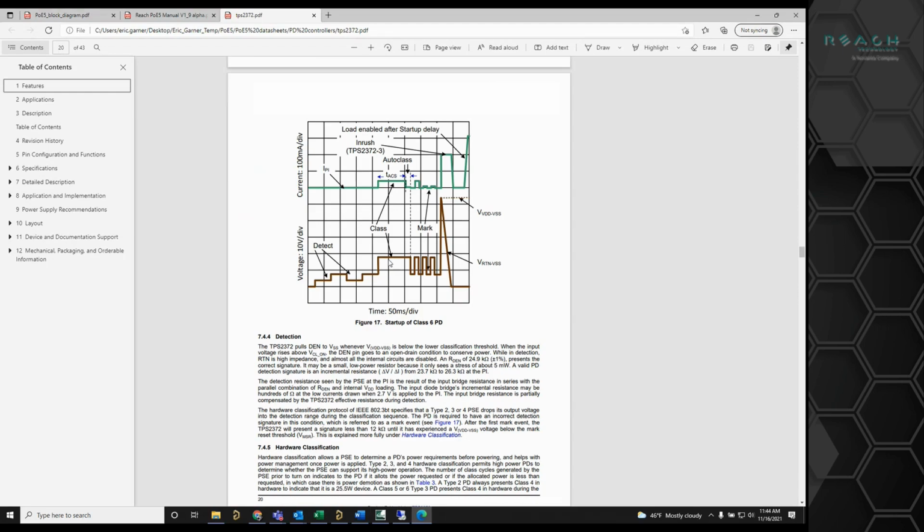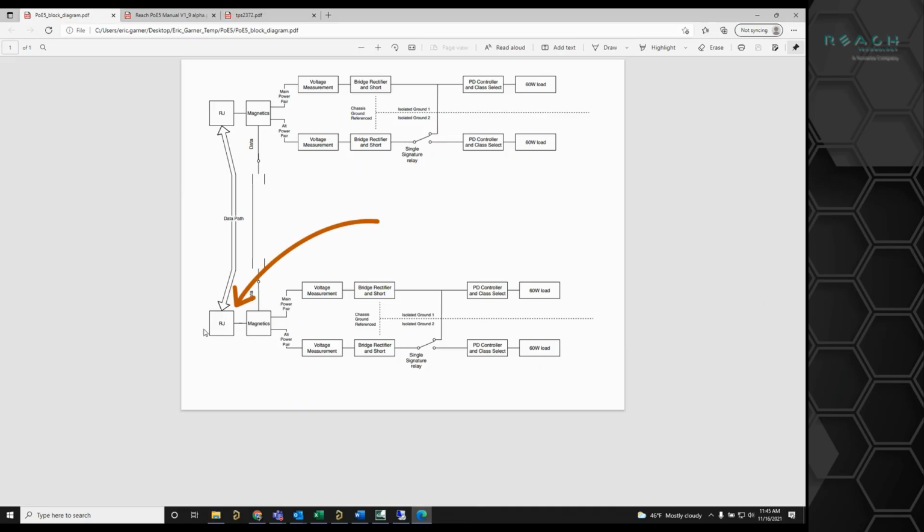I said we're a completely passive device, so if you need to do LLDP testing, you'll need to emulate that externally by putting a link partner on, say, here and doing all the LLDP negotiation that way. This is purely the hardware level, or layer 0, negotiation for power. The data link is always present. Only the power is off.